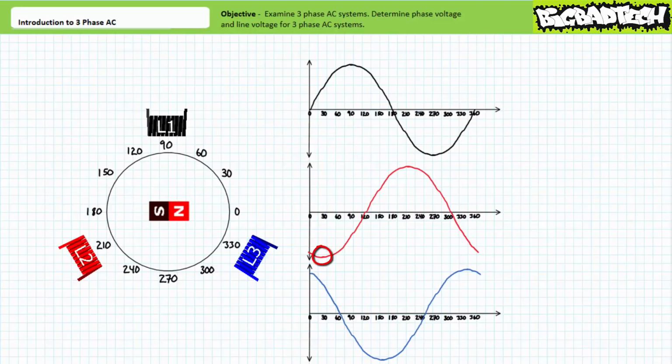Voltage across winding L2 experiences a negative peak at 30 degrees, crosses zero, going positive at 120 degrees, experiences a positive peak at 210 degrees, crosses zero, going negative at 300 degrees, and at an additional 30 degrees, the process would repeat itself. In between these key moments, voltage would again rise and fall as would a sinusoidal function of angular position.